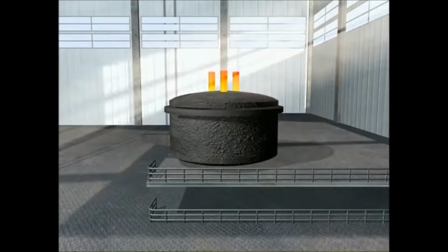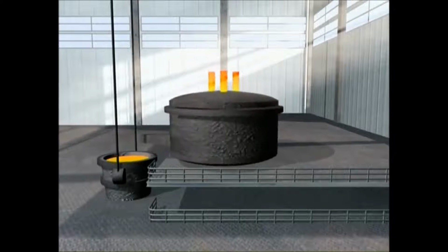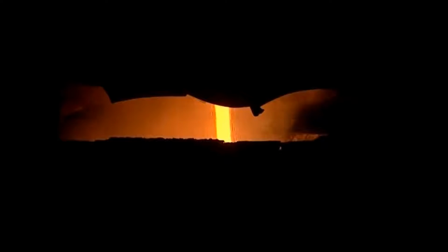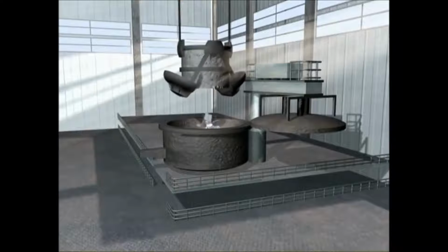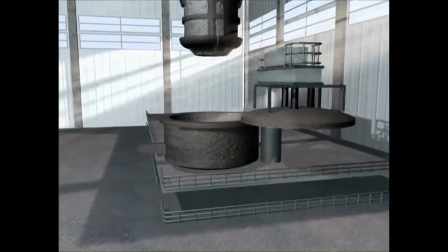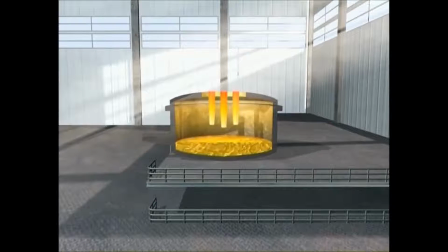The steel is sampled and analysed, and once it reaches its correct temperature and composition, it is tapped off. At this stage, final adjustments to precise customer specifications can be made by adding alloying elements. These furnaces give very precise control over composition and are used for producing a variety of special steels, including alloy steels and stainless steels. Many bulk steels are also increasingly made by this route, and it's expected that EAF output will account for half the world's steel production within a few years.